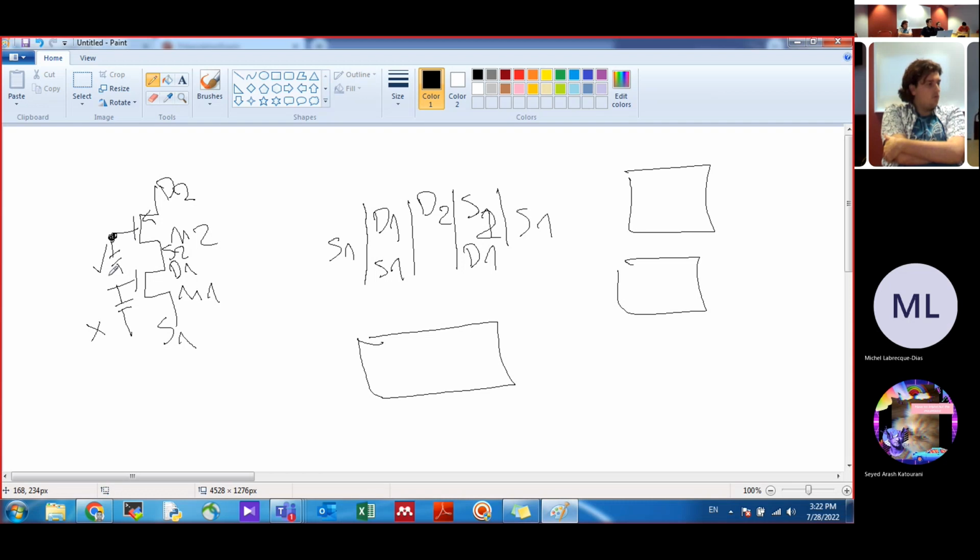If your gate is 60 nanometers, for example, and you have your wire 100 nanometers, the capacitance is really small. But maybe in high frequency. High frequency being from about which range? Gigahertz, okay. Giga, tetra, something like that. In megahertz, I never saw a problem. In low frequency, no. Low gigahertz can start, or even then, it's really when you're at 30 gigahertz, 60.